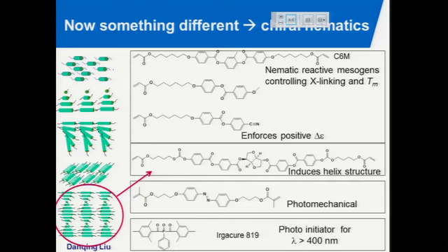So it contains rod-like molecules with these reactive groups. We play with diacrylates and with monoacrylates just to adjust the mechanical properties, the cross-link density of the system. These form cross-links, these form linear polymers. In order to induce the chirality, we added a molecule which has a chiral center, which makes it rotating. It's about 5% of this material in the system.